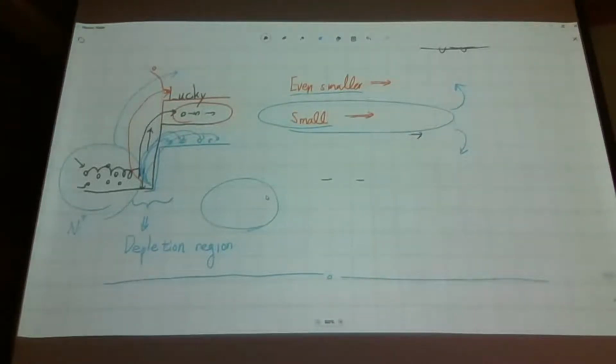So, although at equilibrium, or the 0 voltage difference case, they look quite peaceful, there is no current conduction at all. However, internally, there are two competing mechanisms, drift and diffusion. Their balance is quite delicate, and if we make a slight imbalance of this delicate balance, then our diffusion current will dominate.